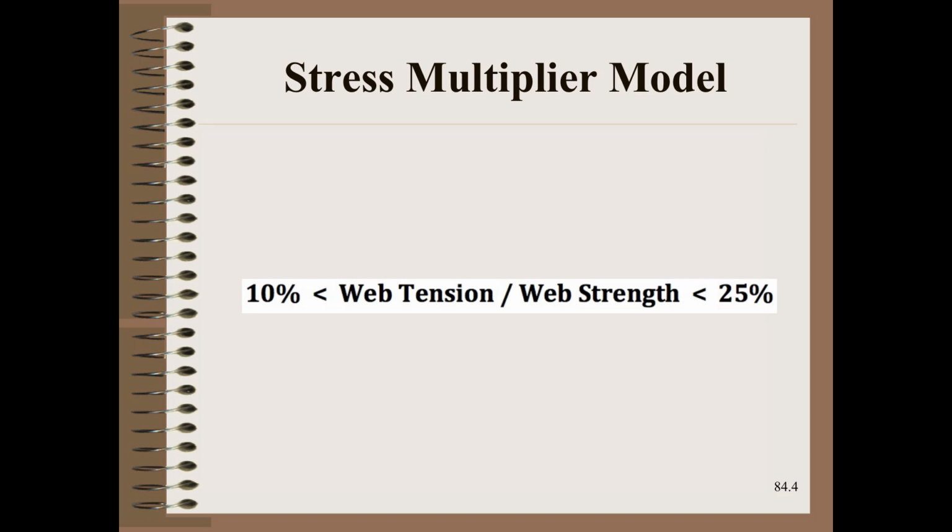Here, we will note for this common starting point guideline, we are in effect running a safety factor of 4 on yield. This safety factor is largely to account for a web and a machine that are less than perfect, such as due to the elements we have already listed. If the web and world were perfect, there would be no need to limit tension to such conservative values for web handling purposes. Also, we should note that the critical direction that we will consider is in the MD. This is a great convenience not having to mess with Moore's circle.